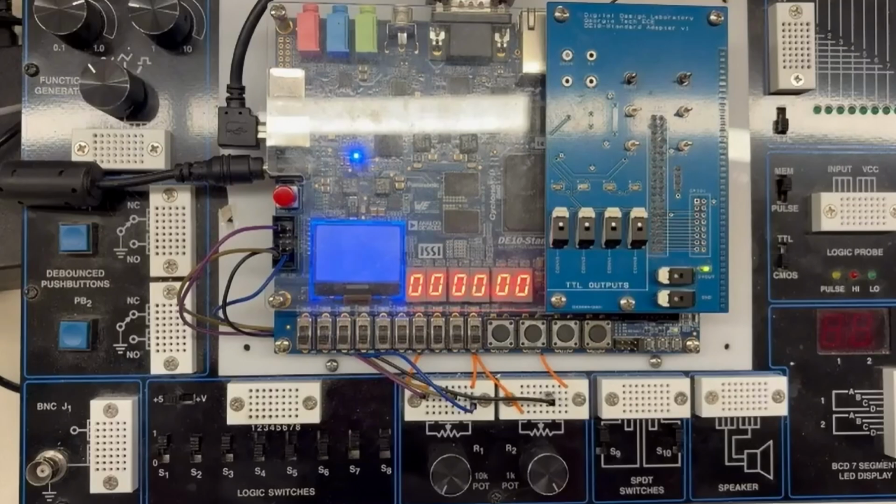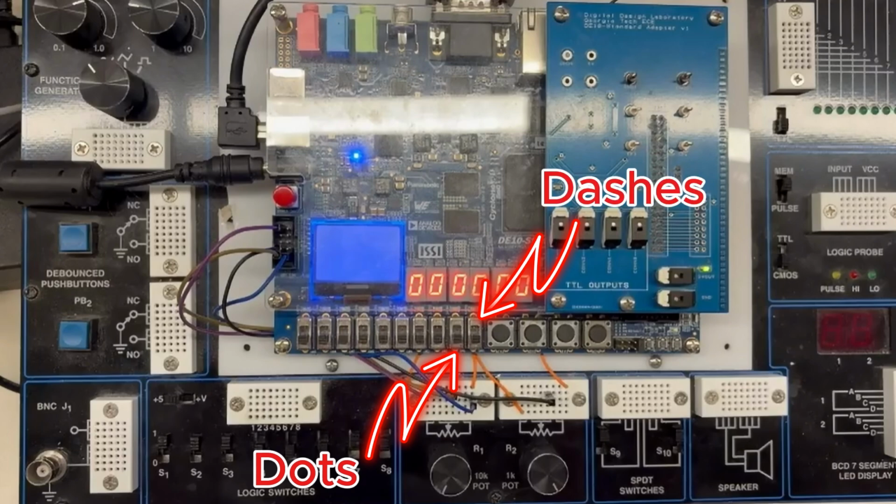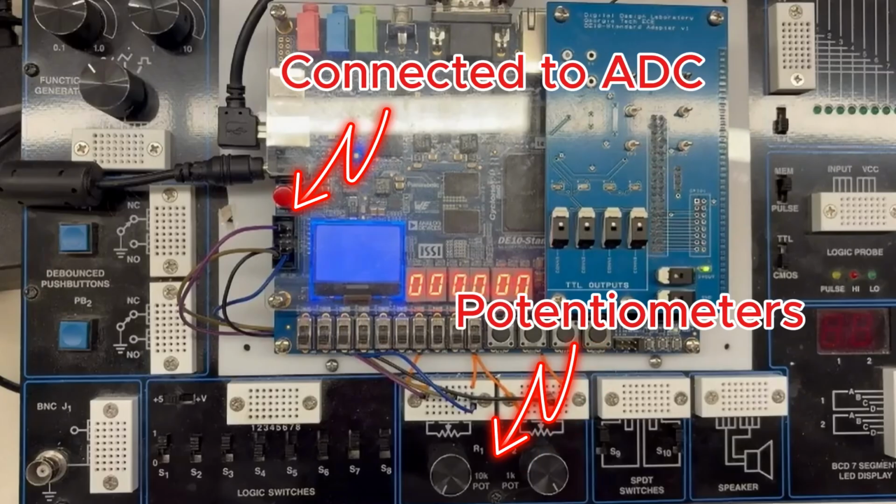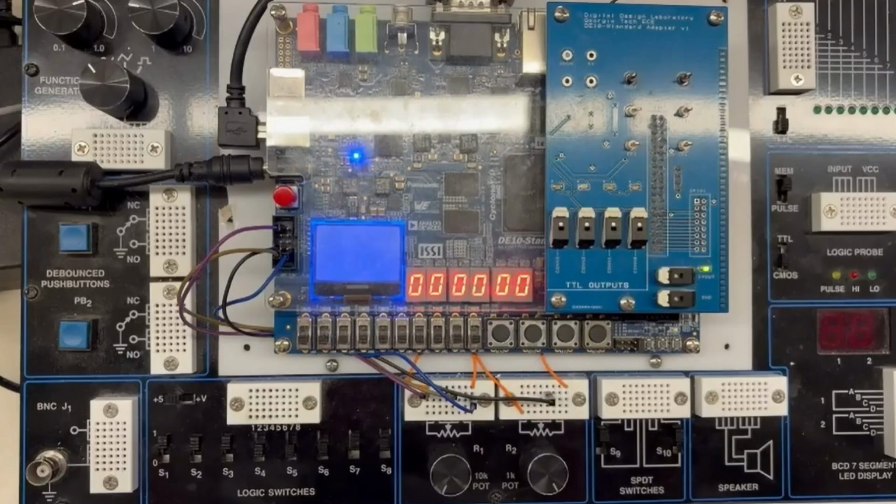For our demo, we use these switches as representing the dots and dashes in Morse code, which would be the flashes of light sending our signal out from the sailors. Switch 1 is going to be the dots, and switch 2 is going to be the dashes. We also have a reset button to make our testing process simpler, and we use the potentiometers to say whether this is a low or a high light signal. That's our way of accounting for light interference, and if this was an actual light sensor, we would have a threshold there to make sure no noise is taken into account when we're looking for this signal with the lights.